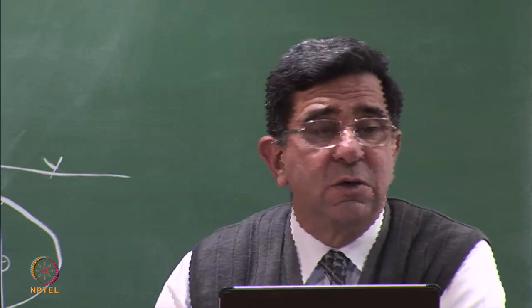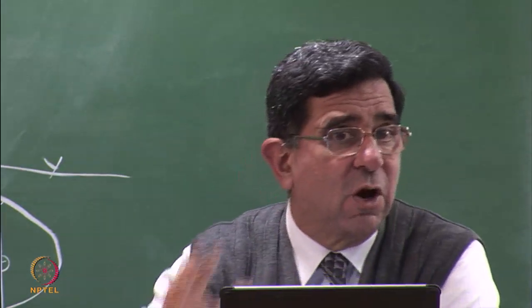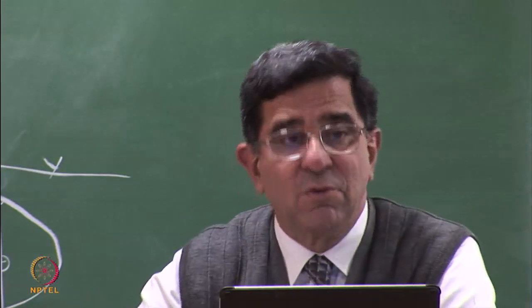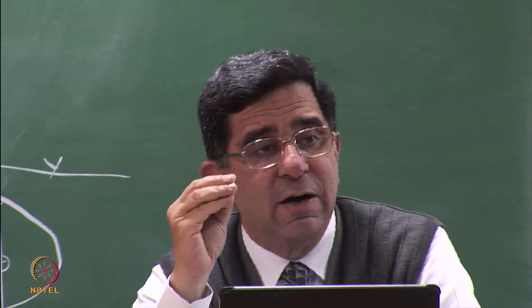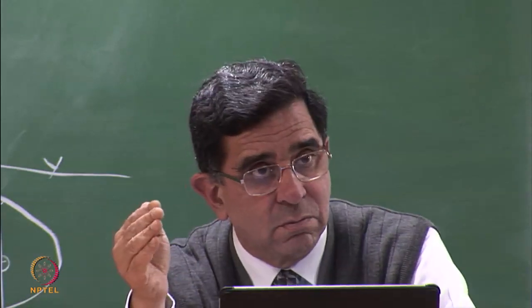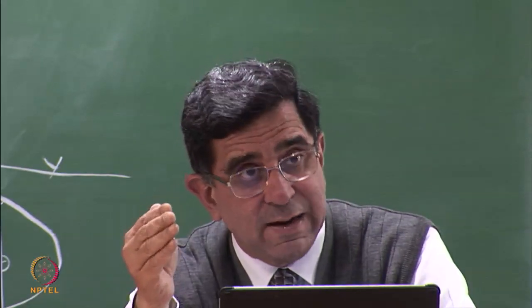Amongst those constituents, the reactive ones are not of interest to you. Why? Because the soil will attenuate them. The non-reactive will go through. So you will really be looking at your contaminant of concern which is non-reactive because it will lead the plume, right? And therefore you can detect it.